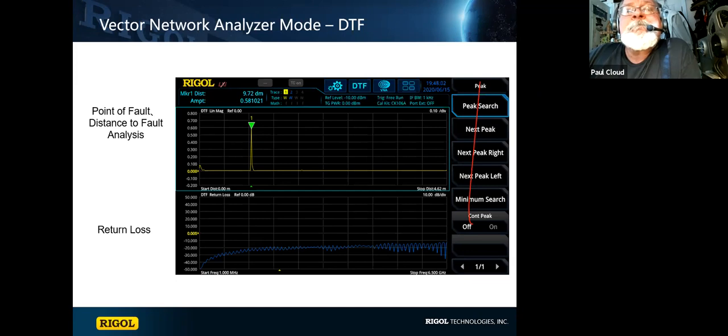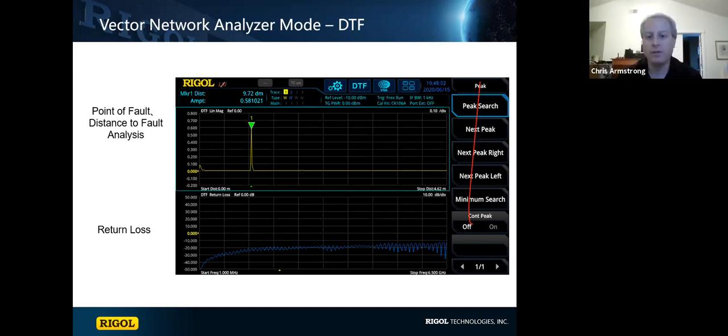My pleasure. One thing to know about the VNAs is that there is a cal kit that you typically want to have, and you can use your own cal kit because you can adjust the parameters as well. But to make any accurate VNA measurements, you have to calibrate that setup essentially every time, right? So you want to do that to make sure you're getting good results.